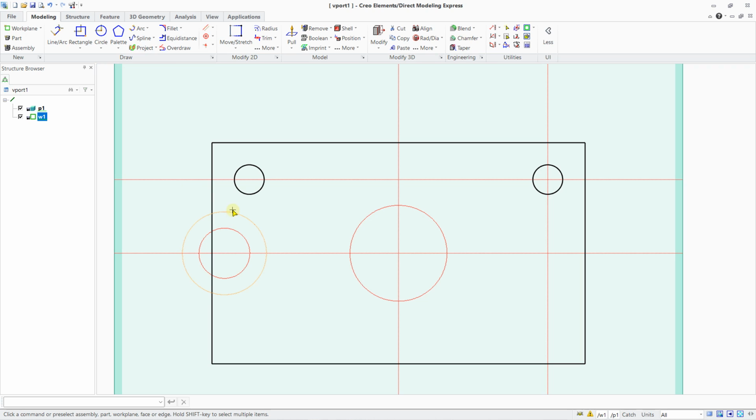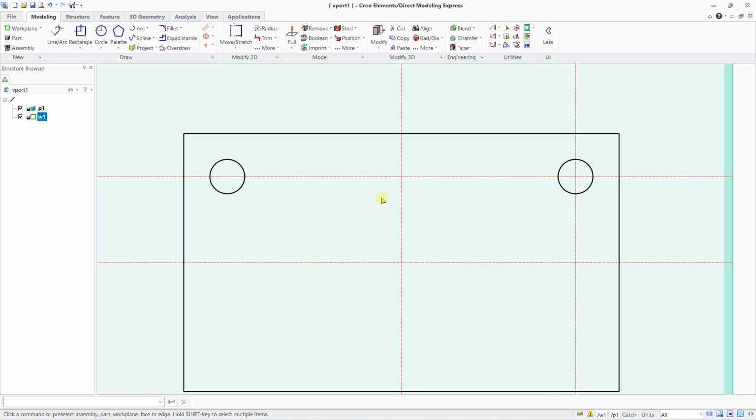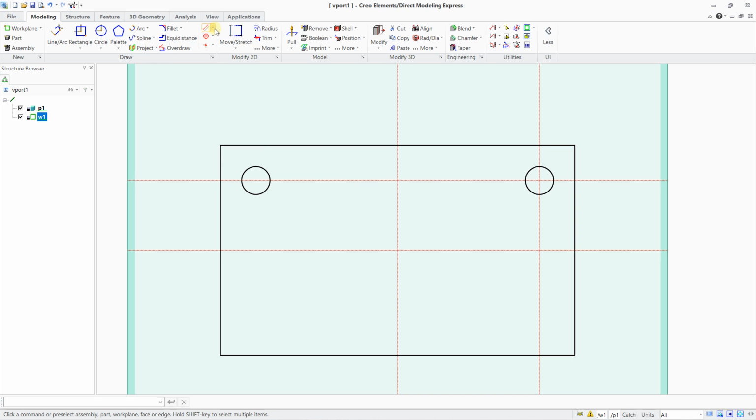If you want to erase an element, you press escape, you click on the element, and if you press delete on the keyboard, you can remove this. Let's continue. I'm going to click here, activate, for example, select my circle tool again, and just go on this area and just start from this point,